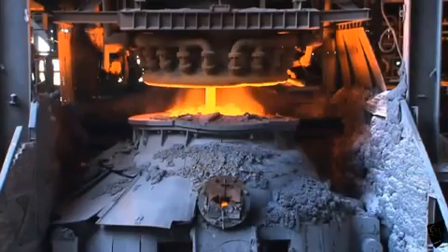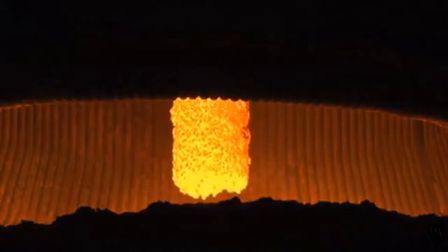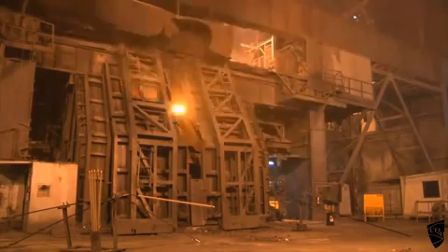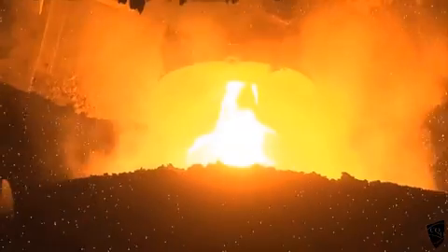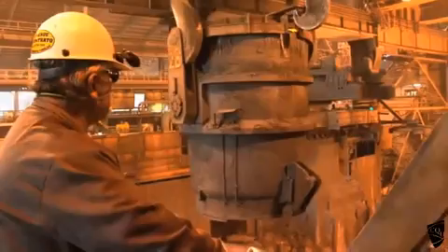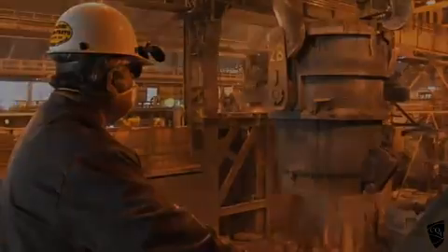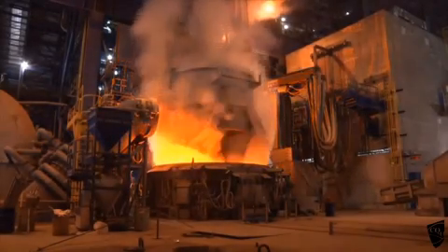For refining, oxygen, argon, and nitrogen are injected into the mix under pressure through tubes known as lances connected at the top and bottom of the converter. After a period averaging 45 minutes, liquid steel is obtained. The steel is poured into large ladles and ferroalloys are added in order to adjust its chemical makeup to match the requirements of the material ordered by our clients.